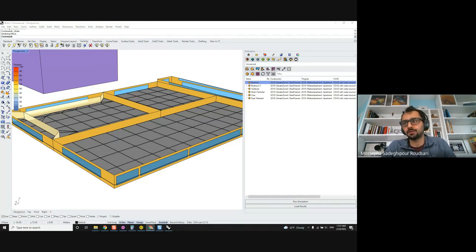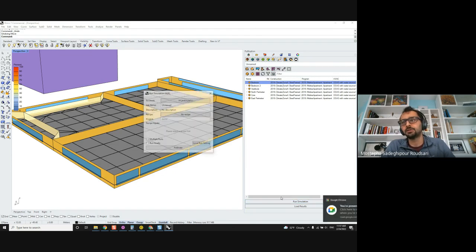Again, it depends on the recipe, and the answer for most of the recipes is yes. So when you set up a recipe, check the recipe input. Some of them you have to set up when you set the WEA file or a weather file, so you just have a partial weather file. Some of them you put the whole weather file and then you set up the analysis period. It's different recipe by recipe, but generally speaking, most of the recipes allow you to do that.